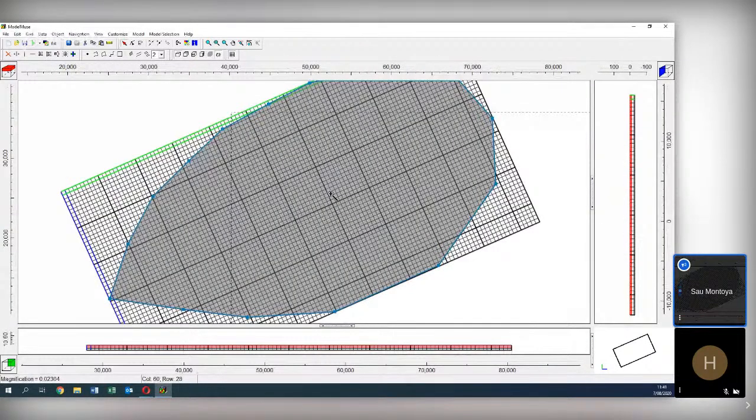But now what I'm going to tell you is how to do local refinements. Let's do a local refinement because here, for example, this is my study area. I want to have more cells here, but here I'm not very interested in what is going on. So for example, here the refinement will be 2000, while here it will be 500. How do I do that?